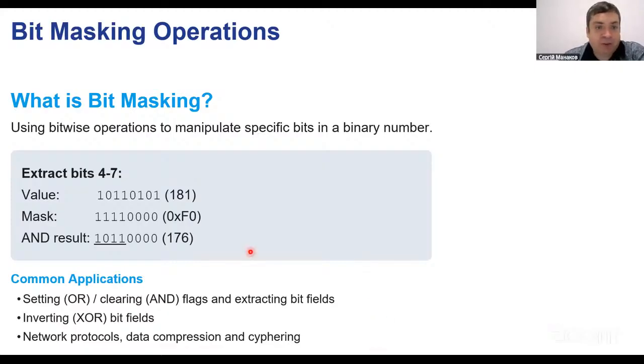So these are masking operations, and you may ask, why should we need to know it? Just imagine you have an Arduino board and you want to control 8 LEDs, 8 little lamps, and you have an 8-bit physical port with 8 physical pins with each LED on each pin.